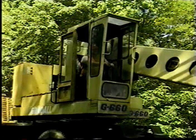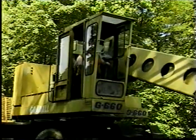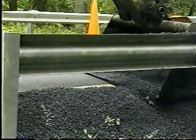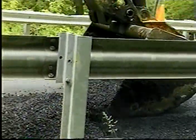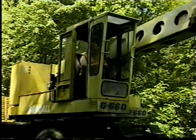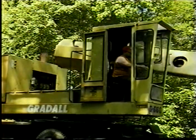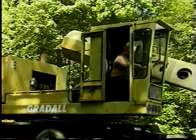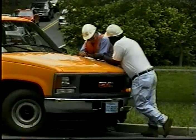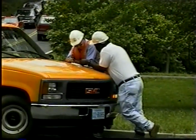Ditch cross-sectional modifications can often be combined with debris removal operations or slope dressing operations. A safer cross-section can often be obtained by converting V-ditches to flat-bottom ditches and using the extra material removed to better blend drainage inlets to existing terrain. In some cases, ditch relocation can represent the safest improvement. Slope flattening can push the ditch further away from the roadway, both of which produce a safer roadside. Ditches near crossroads or driveways can be relocated to remove the pocket that results when ditch culverts are used.